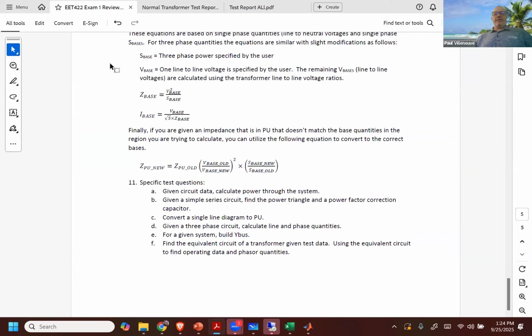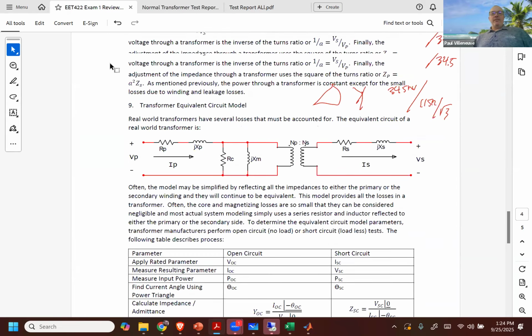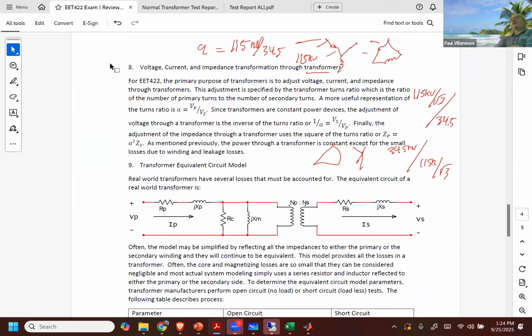I can tell you right here. This is the equivalent circuit of a transformer. What type of circuit would that be indicative of? Is it a resistive inductive circuit or a resistive capacitive circuit? It's resistive and inductive, right? There are no capacitors. So based on ELI the ICE man, this is an inductive and resistive circuit.